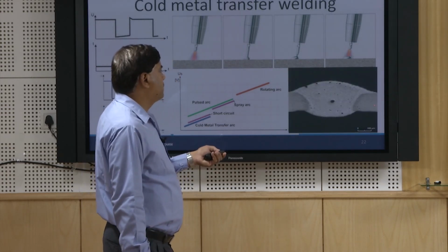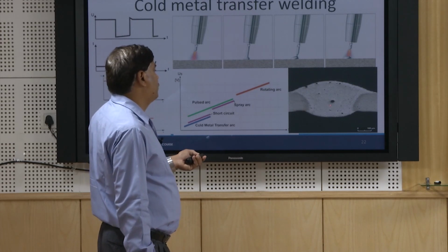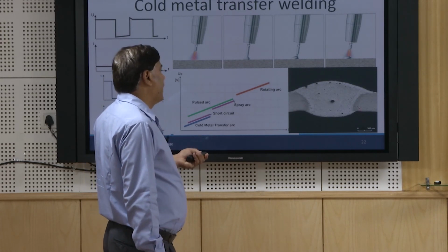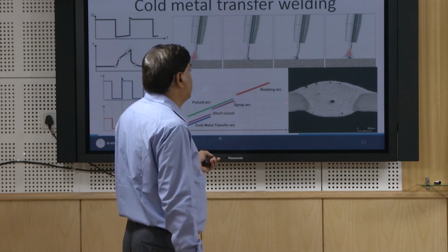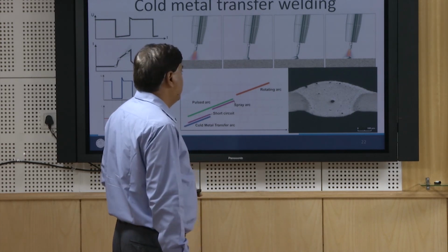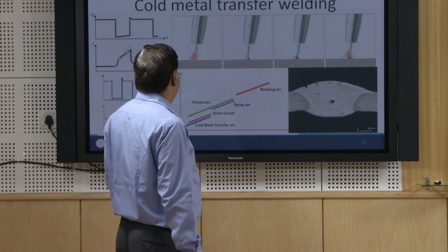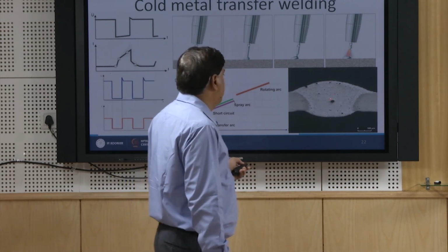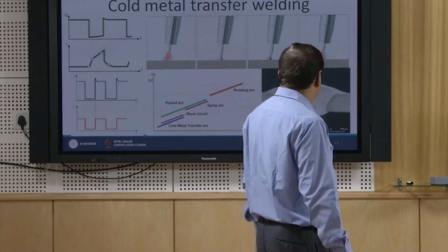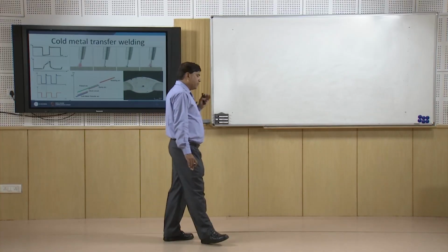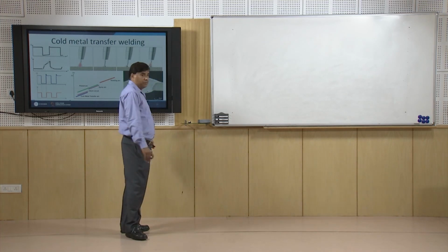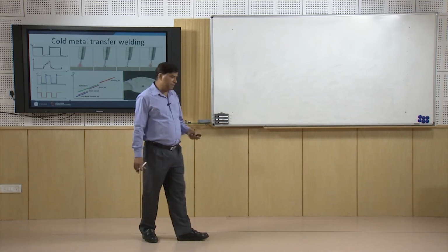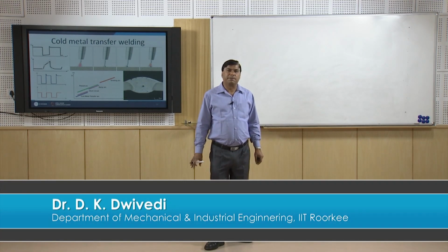This is a typical experiment used for developing joints of thin sheets, and the joint was made using the CMT process. However, it shows some pores and blowholes. Although the pores are of very small size, maybe 50 to 60 micrometers, they are very isolated. So, now we will conclude this presentation.